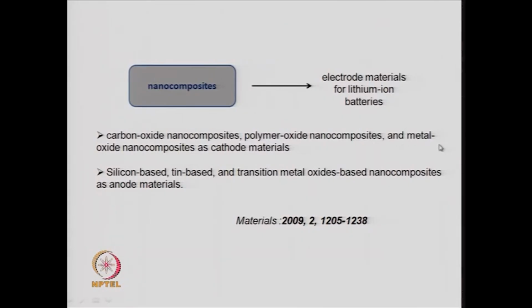That will also give you nanocomposites, and many times such composites made of a metal oxide with a metal particle are called cermets, because the metal oxide is a ceramic, which is a non-conducting, high temperature refractory material, and that ceramic with a metal will typically be called a cermet. And of course, if one of them is nano size, then it will be a nanocomposite or a nano cermet. And these combinations have been used to act as cathode materials in lithium ion batteries.